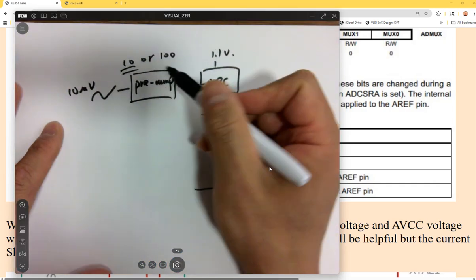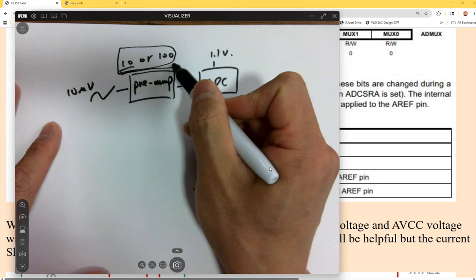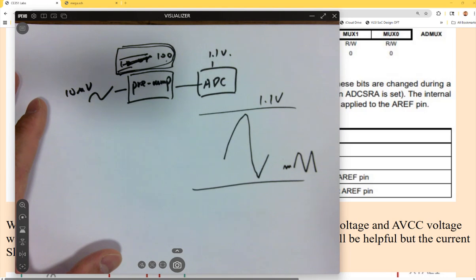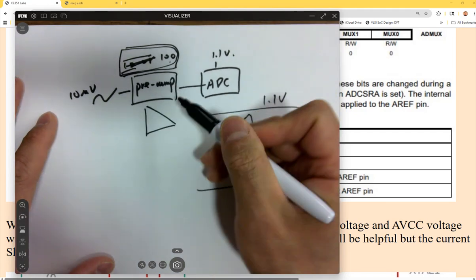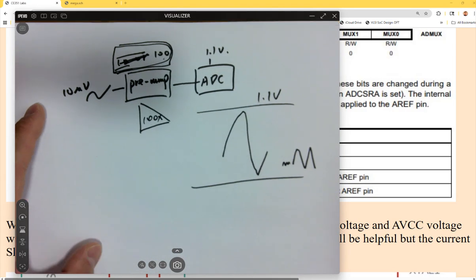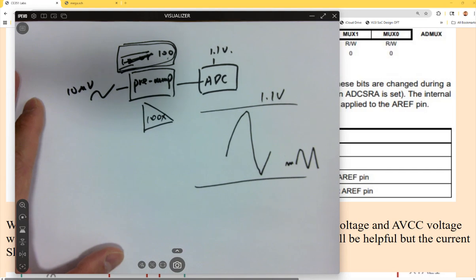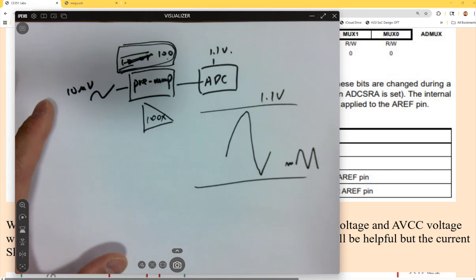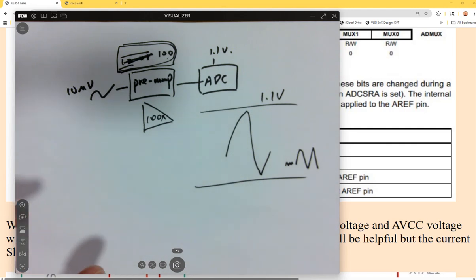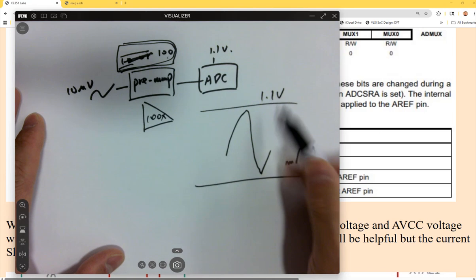So what's the common amplification per stage, and why? For example, we want to use 100. Would you like to use one amplification with 100x gain or multiple stages, and how many stages usually? No more than 20, depending on the quality of the amplifier, but usually 5, 10, but no more than 20. When it's getting closer to 20, you should feel nervous because it's going to amplify the noise as well, eventually eating up your resolution.